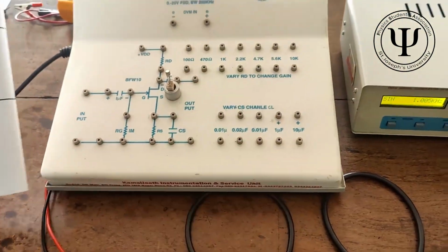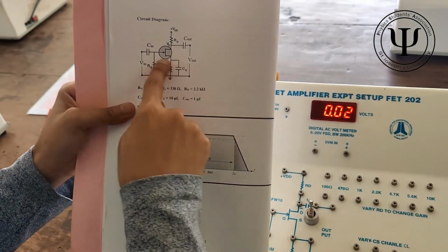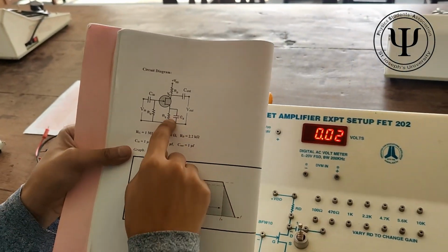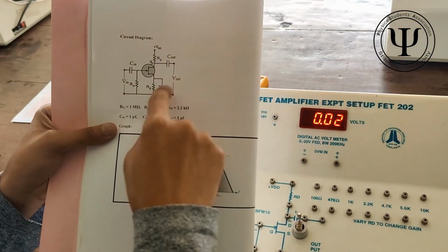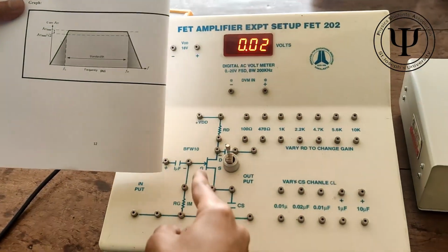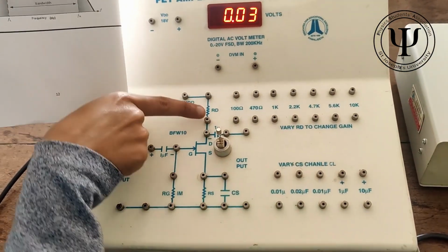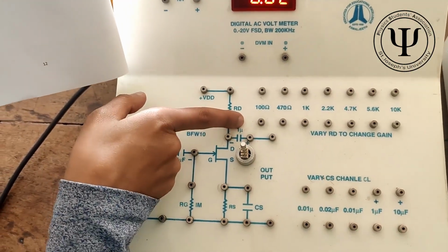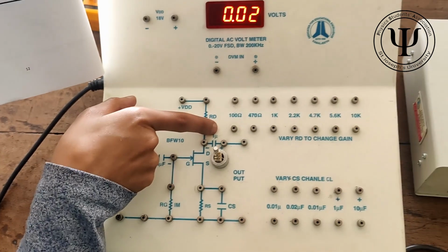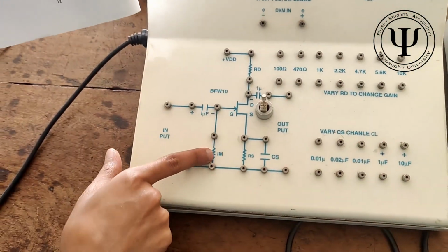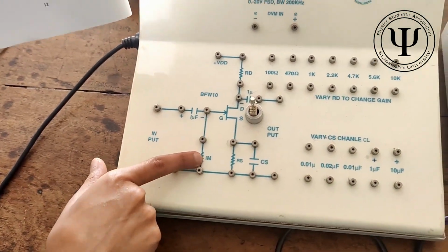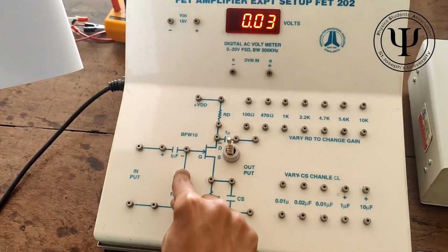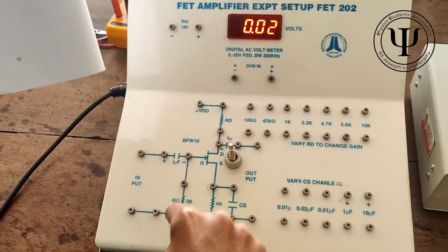issue. Now, our task is to connect this circuit as shown in your figure. Make sure that you memorize it, yeah? Now, you're supposed to connect these resistances and these capacitances. The work is easy for you because where it says the value of the capacitance or the resistance, such as 1 microfarad and 1 mega ohm in this case, these are connected internally. So you don't need to connect wires from here to here.